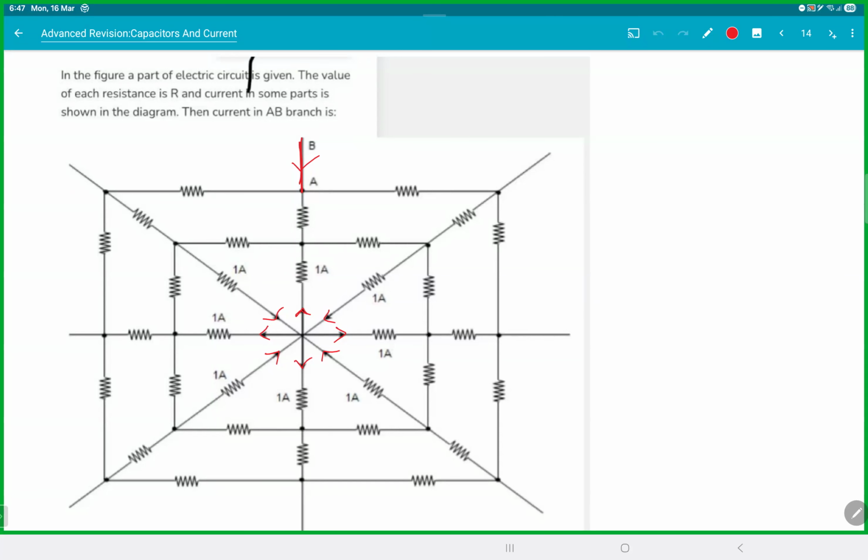So how do we start this question? The idea is this: let all resistors be R. Anyway, it doesn't matter. Let R be 1. Start from the center. Let this be 0. If this is 0, from junction law, this must be how much? Current always flows from higher to lower potential. This is +1. If that is +1, this is -1.